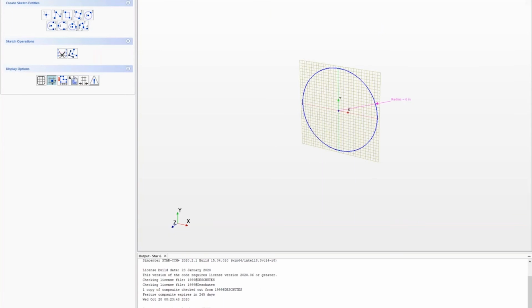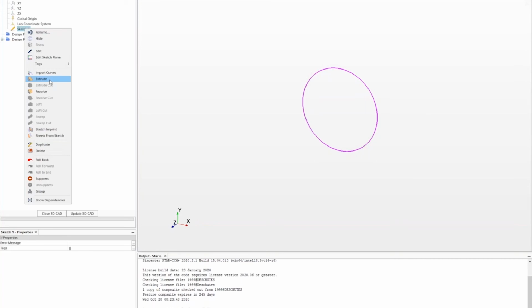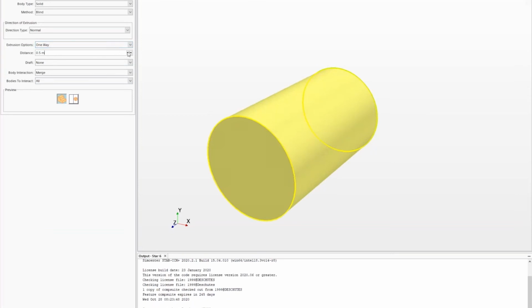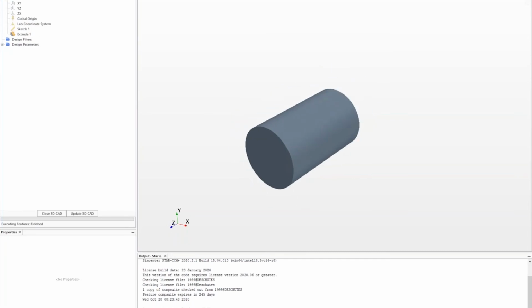exposed. So once we have our shape, we can then go to our shape and extrude this, and say if this ends up being a pipe or something, we have our distance here of how long we'd want that. Again, you could expose that dimension for later usage and reflection to go back to, and hit OK. And now we have our first part and our first body that shows up here. And that's basically how you would create geometry and manipulate geometry.